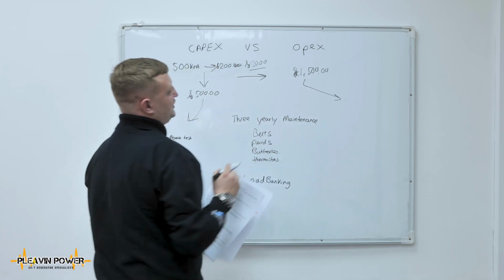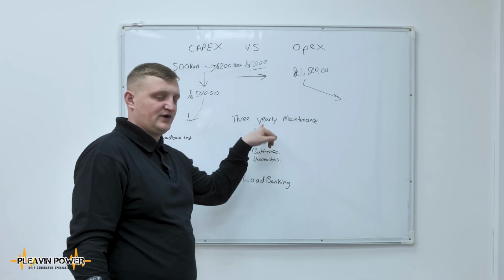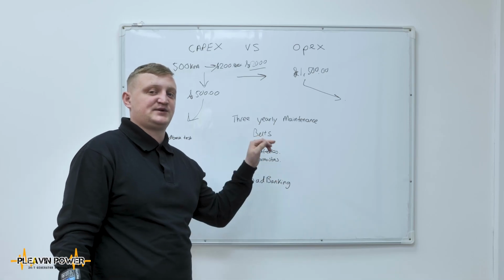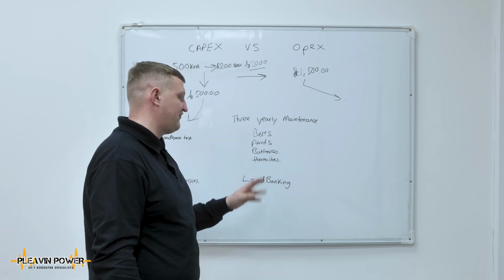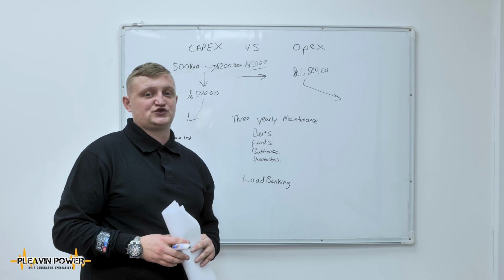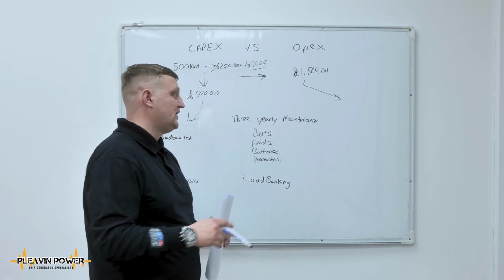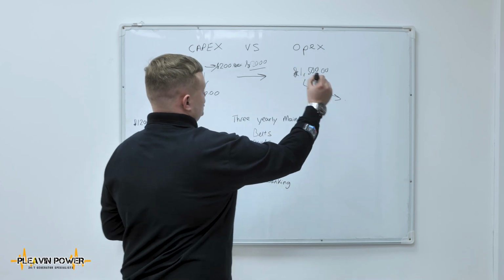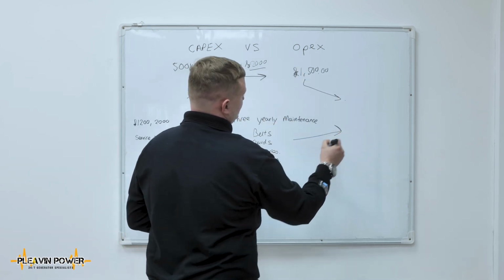Now, you could argue that you don't need to carry out load bank testing until such time that this intrusive work is completed to verify that the work has been done to a satisfactory standard and the equipment remains in a healthy condition. However, load banking changes, and in some cases it is carried out every 6 months or once a quarter, depending on who the end user is and how critical the plant is to the client. Operational expenditure should not increase unless you budget for these works to be carried out during the course of a service contract.